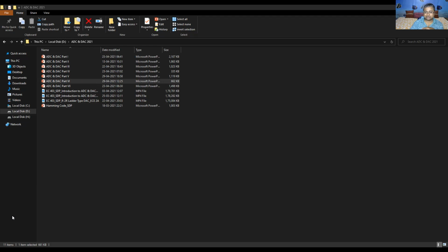Now the n-bit up counter will start counting in the up direction because the clock is passed through the AND gate. This is 1, this is 1, this is 1, so the counter will count in the up direction. The moment V1 goes below 0, the clock pulse reaches the clock input terminal of the counter, which is initially cleared to zeros.